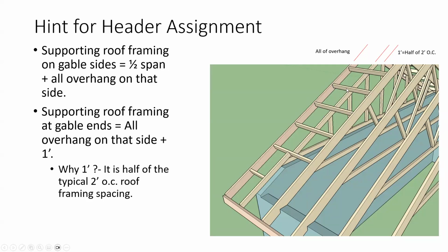What those are for is they're kind of making it like a teeter-totter, right? Because otherwise, if it's just the plywood sticking out with some wood stuck underneath it and some big 300-pound carpenters out on a 2-foot gable end overhang, it's going to be a problem. So we need to stabilize it. So what we do is we run these 2x4s back to bring that load back in and support that overhang.